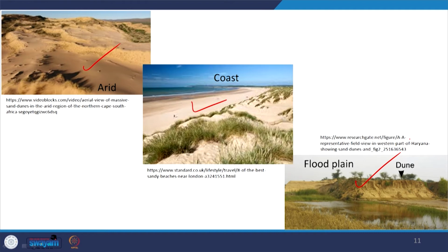If you see the geological map of the Indian subcontinent, particularly the Indo-Gangetic plain, you will see a number of Aeolian ridges within the fluvial plain. Those Aeolian ridges are nothing but the result of wind action reworking these fluvially deposited sediments, mostly silt and clay, and forming ridges. The ridges are mostly occupied by loess. Loess is loose material, mostly silt and clay grade particles.